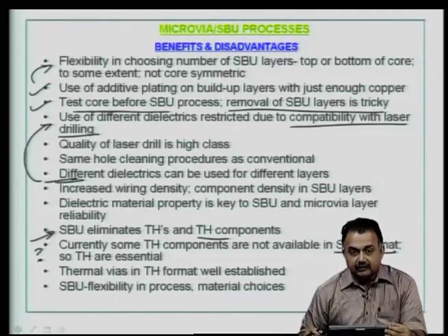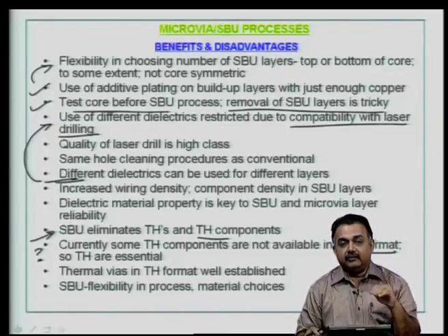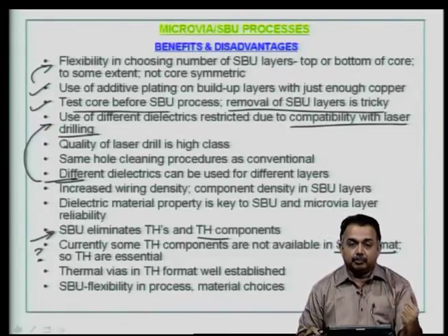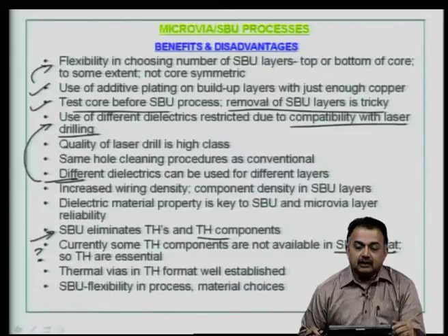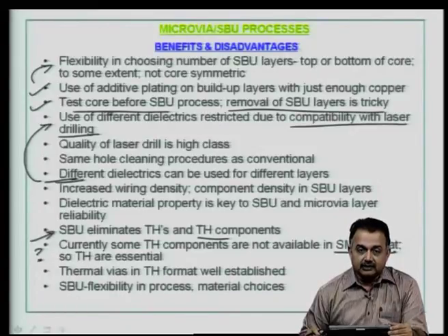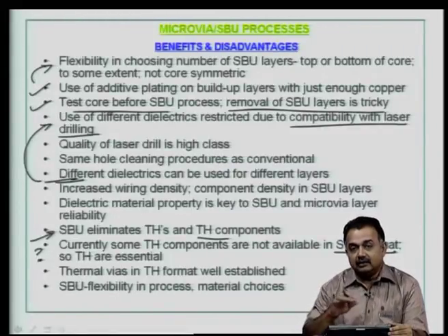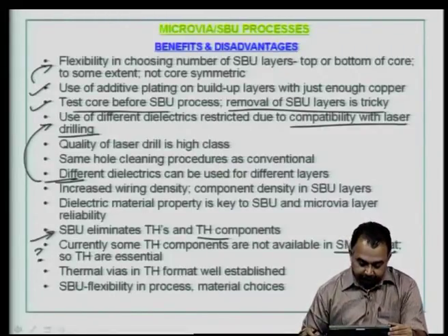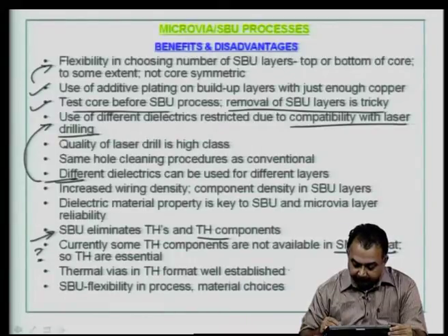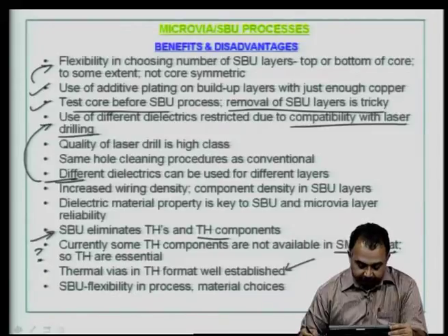But in the case of a microvia, where the lands of the microvia are used for the footprint of a BGA, it is being used as a thermal via, but there are some limitations as to how much heat these microvias as well as the inner layers can take. So, this is a debatable issue, it goes by design to design.